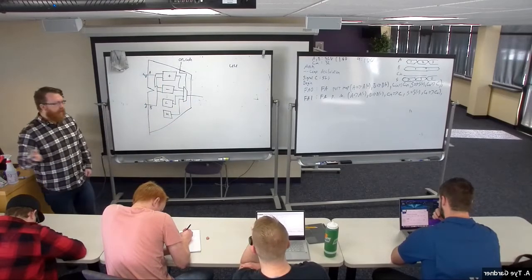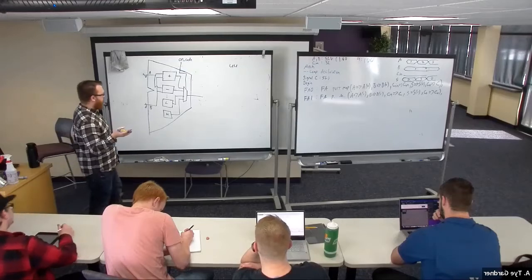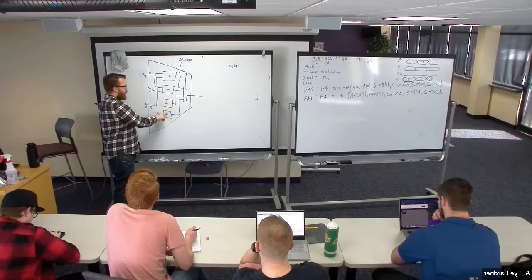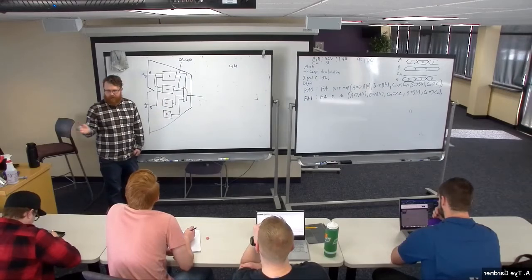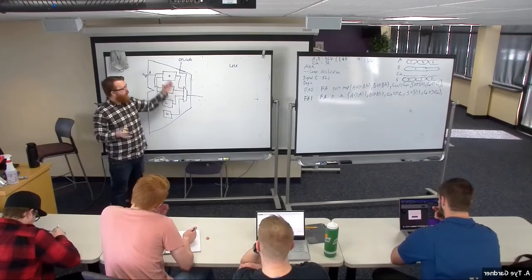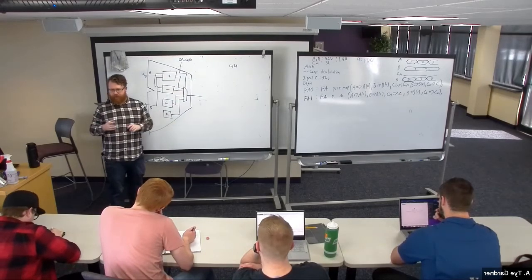It turns out that the ALU is doing too much work, in a way, in that it's doing the addition, subtraction, the load, hold all at the same time and making each of those results available to the mux. And then the opcode is just going to say, which one do I want?